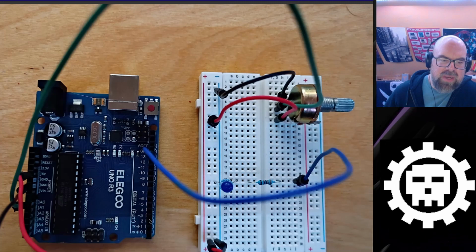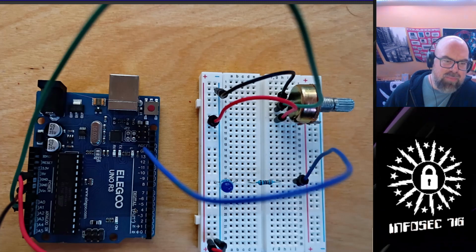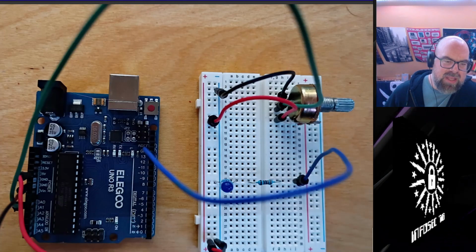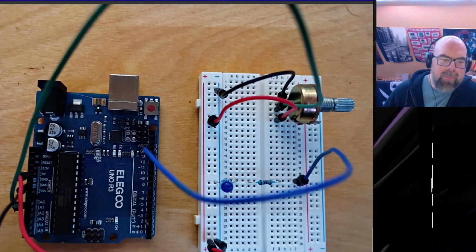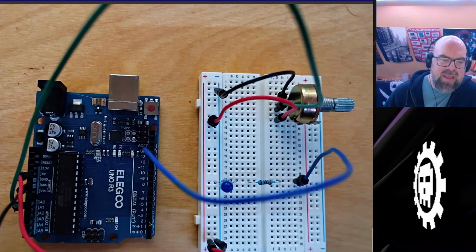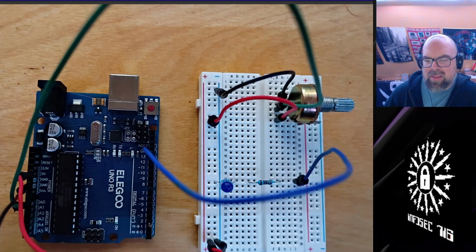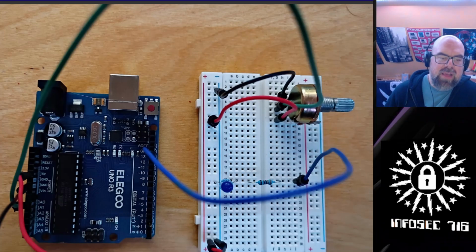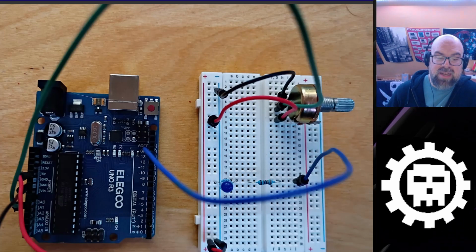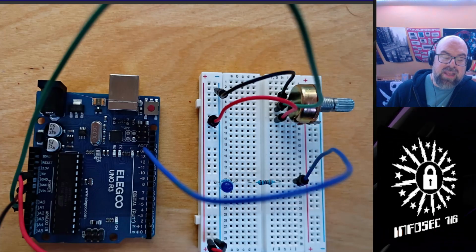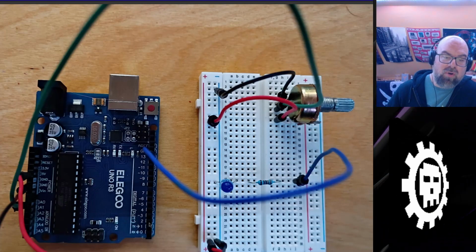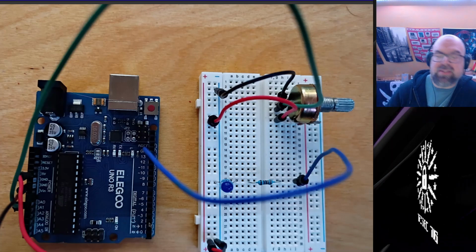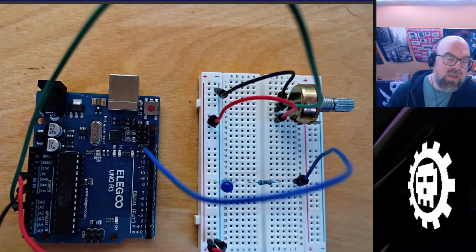Now you probably remember in our last video, our button was connected to pin 2. Pin 2 is a digital input, and we can see that printed right here on the board, digital input. And then PWM, we'll talk about that a little bit in a minute. But that means that this pin can only detect digital values. Is it on? Is it off? That's it. If you have a digital sound sensor, it's basically, is the sound above the threshold or below the threshold? There's no measurement of how much signal there is. It's either above or below a threshold.